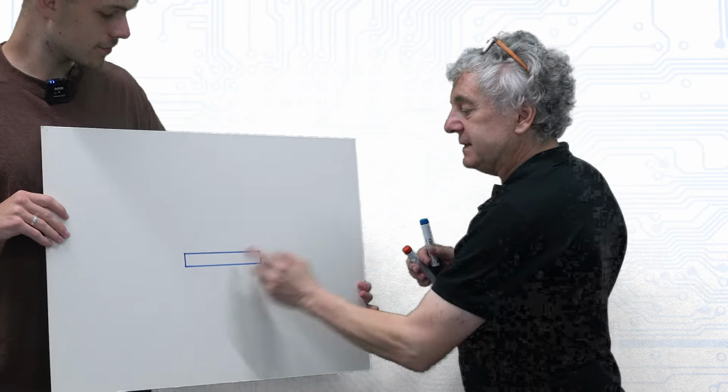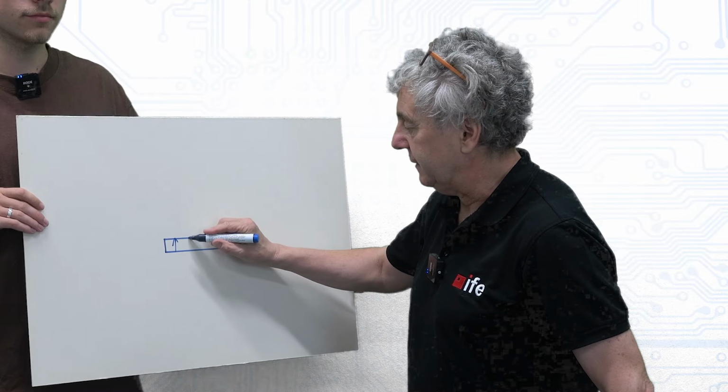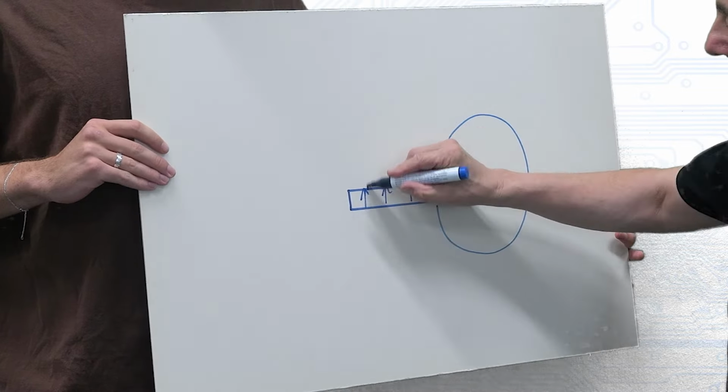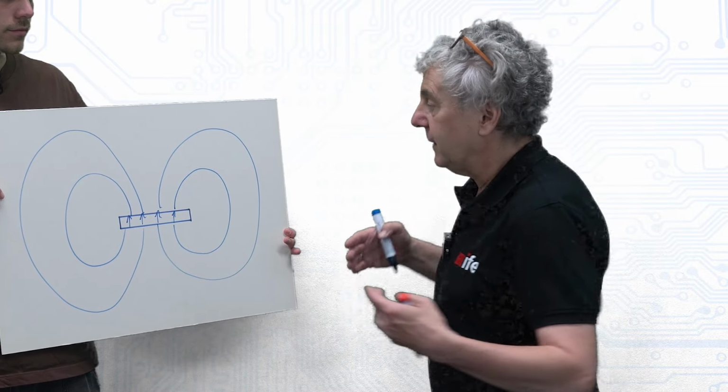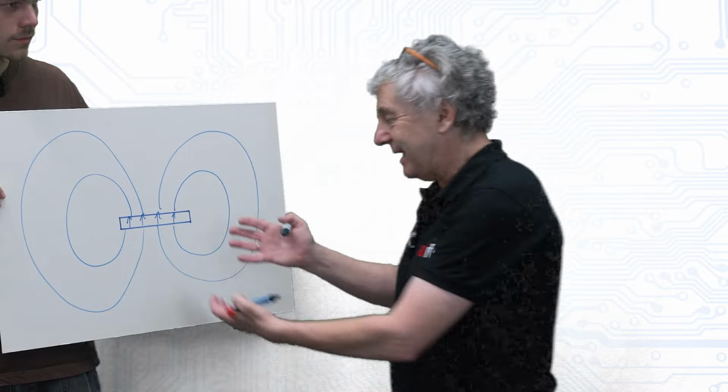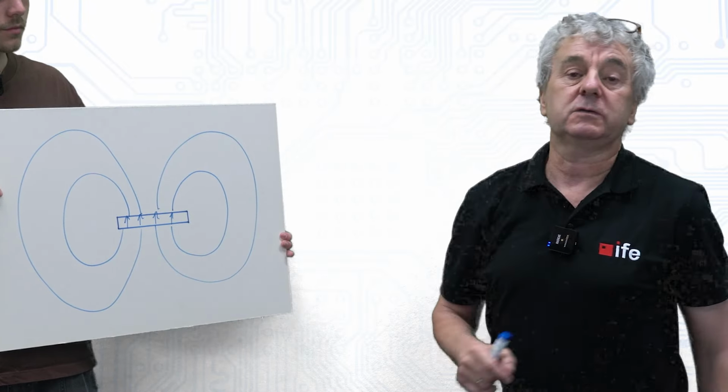This is a slot, so this reaction current, this virtual current, also is visible here in the slot because it's a thin metal slot. So we would see the same pattern of this current flowing on the backside. But this current on the backside would start also to radiate. So what we see in a perfect metal, we see perfect shield. But in a slotted metal, we see the field which is needed to compensate the current in the slot. So this is the radiation, or this is the antenna current structure, which still continues to radiate.